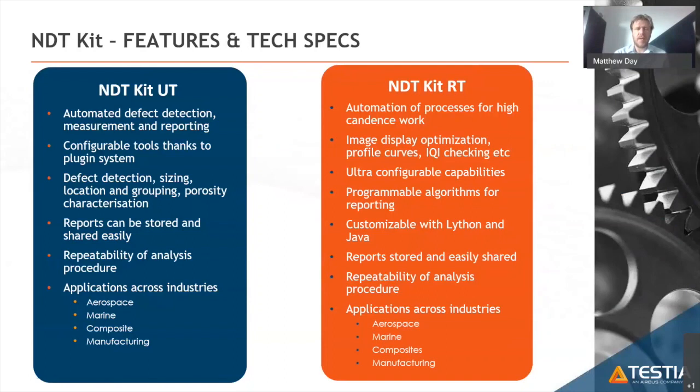Similar for radiography. It's automation of processes for high volume work, image display optimization, profile curves, IQI checking, and it is ultra configurable. Programmable algorithms for reporting and customizable with Python and Java computer languages.